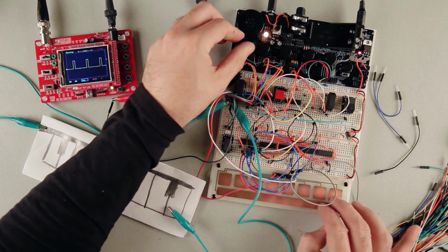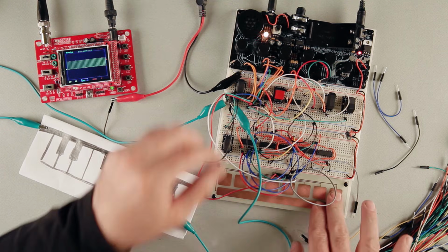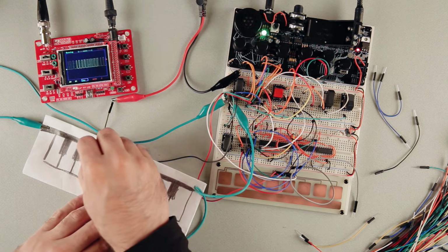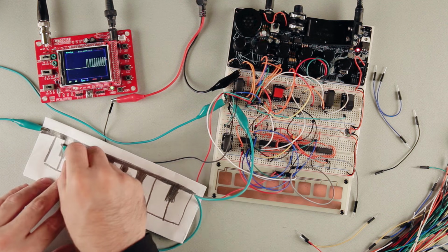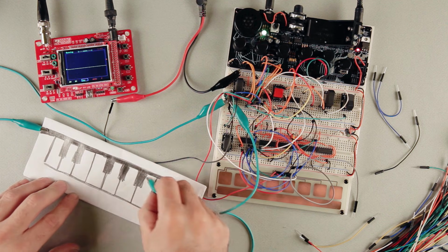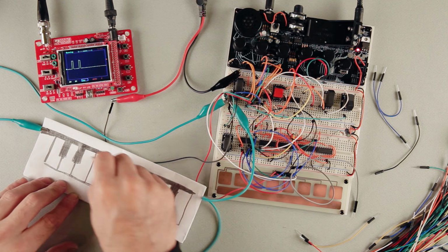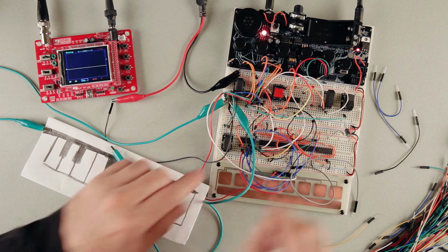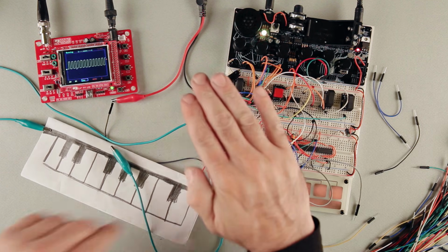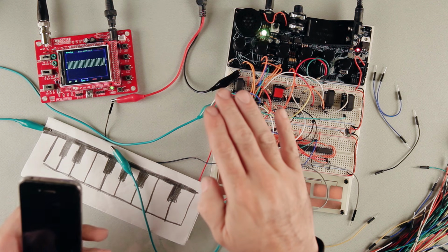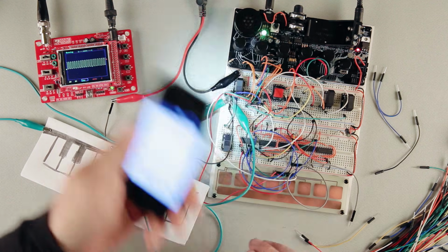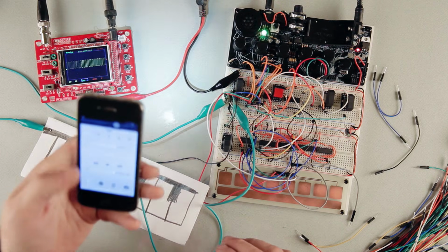And then we're going to look at a bunch of ways to control the oscillators, so with touch, or this is using graphite. You can draw on a piece of paper, and then the resistance of the graphite will allow you to change the pitch of the oscillator. We're also going to do light control, and then you can do things like use your phone or anything that makes light, and you can change the pitch.